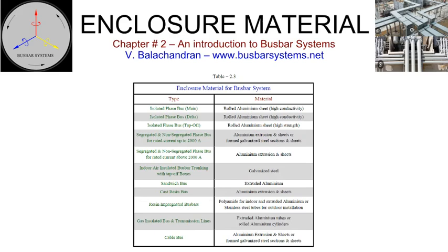Where alternatives are acceptable, the selection of the enclosure material will be governed by specific requirements of mechanical strength and resistance to corrosion, provided its temperature at the hotspot under rated conductor current meets the specification requirements. The enclosure may be given a coat of paint for additional environmental protection and improved emissivity.